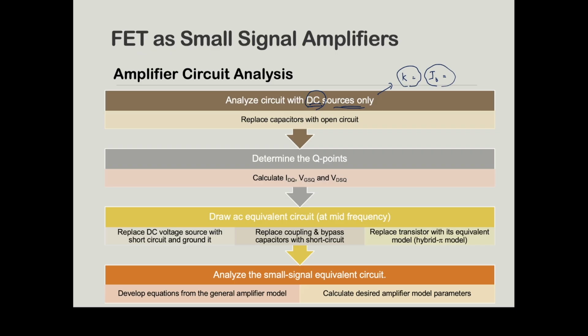In DC analysis, we replace all the capacitors with open circuits, and then determine the Q points: IDQ, VGSQ, and VDSQ. This is for your DC analysis.